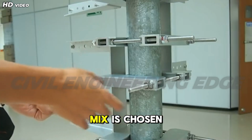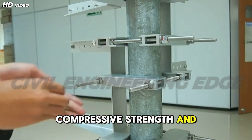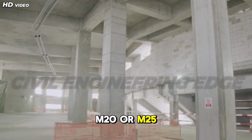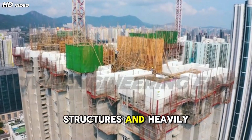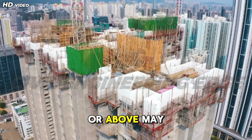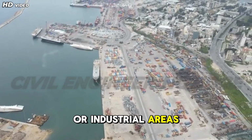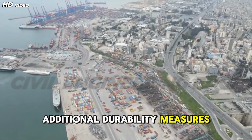The concrete mix is chosen primarily based on required compressive strength and durability. For residential and low-rise buildings, M20 or M25 concrete is commonly used. For high-rise structures and heavily loaded columns, higher grades such as M30 or above may be required. Exposure conditions, such as marine environments or industrial areas, may necessitate higher grades and additional durability measures.